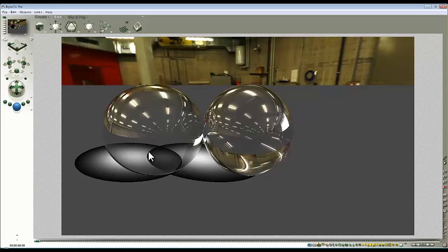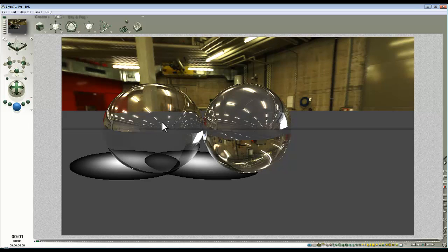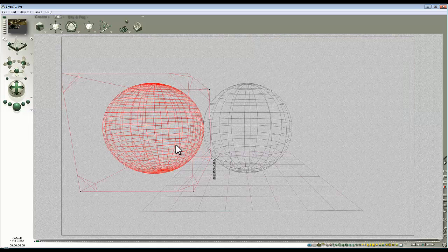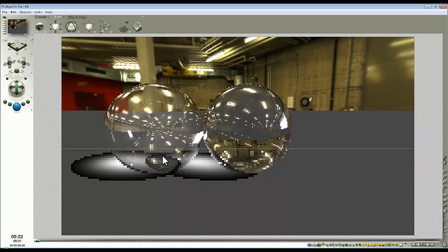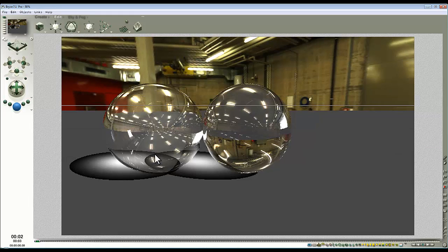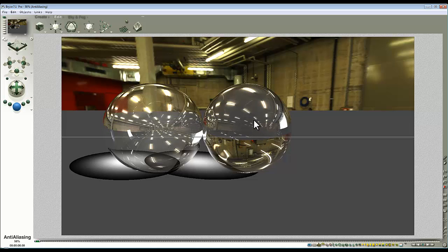So the thin wall material has a refractive index of glass, but there is something missing. There is no internal reflection of the inside. This is due to the nature of the surfaces only have one side, and that in this case this isn't helping us. The inner surface is not doing any reflection for us, but if I put on the inner surface some reflection like so, is that going to throw things out in a different way? That don't look too bad actually. I only needed a small amount of reflection, you'll note, because the high dynamic range in background is providing a lot. So the other thing to consider is that there is some attenuation in the reflection when it's coming to face the camera.